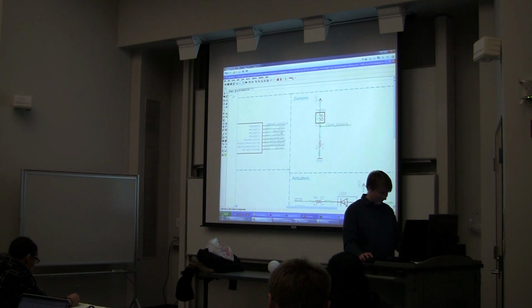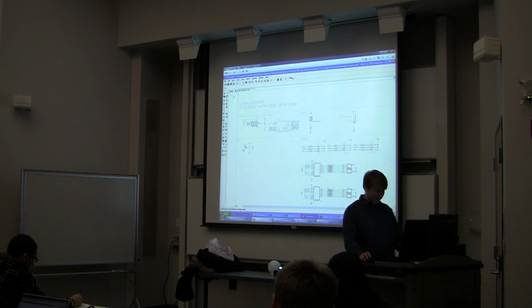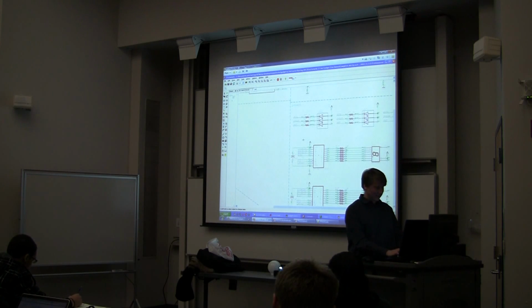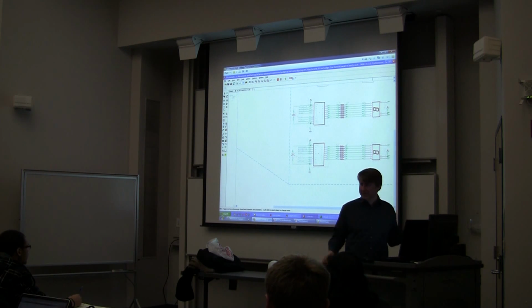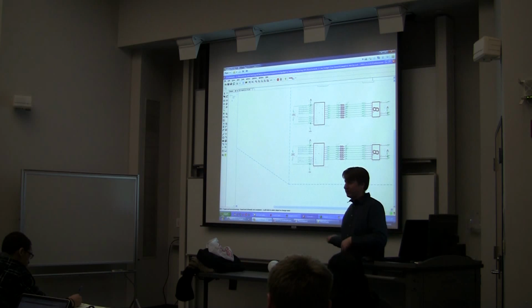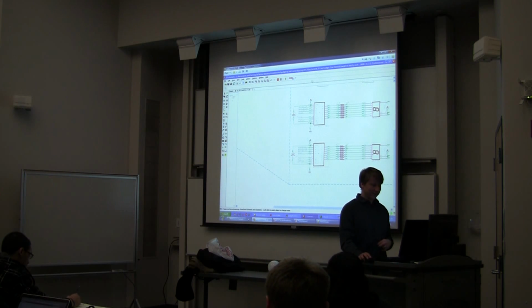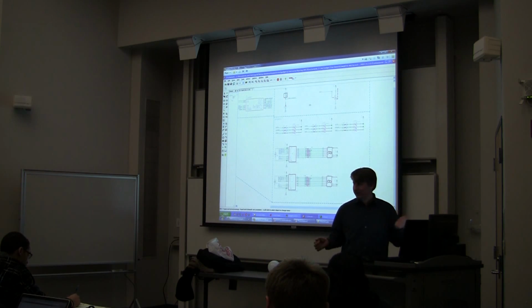I'm going to name this, actually I'm going to name this button latch 1 again, because it bothers me to have latch 2 instead of latch 1. Okay, so now I got latch 1, I got latch 2. Double check my ERC. Oh no! I got more of these errors. Let me improve them. You really want to make sure that you have no ERC errors before you go to layout. It's also good if you sort of avoid logical errors, like I forgot all my resistors.